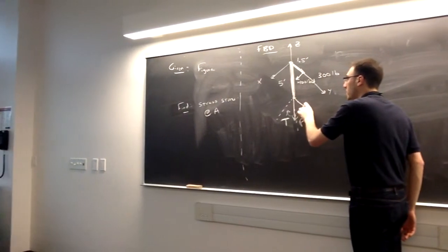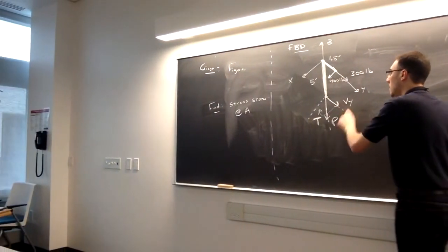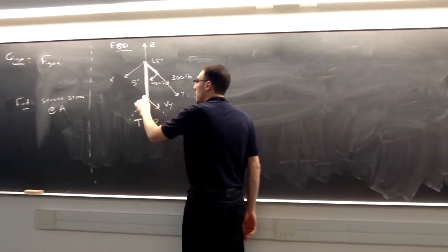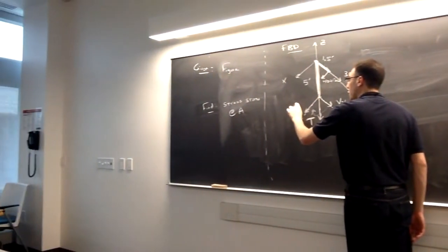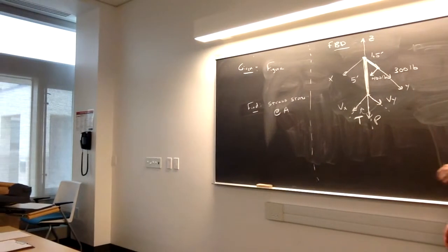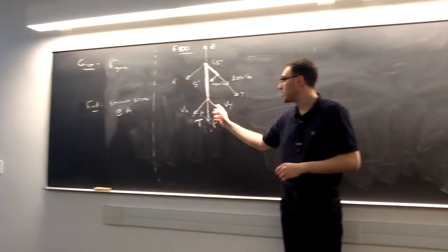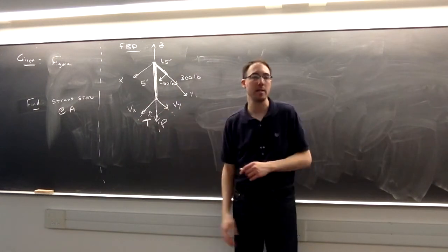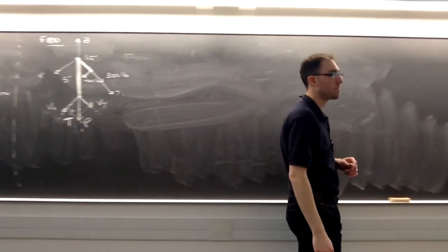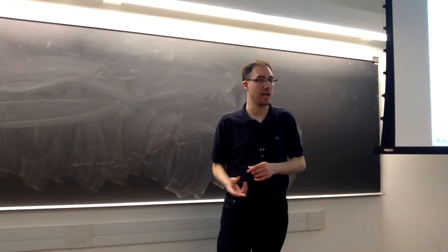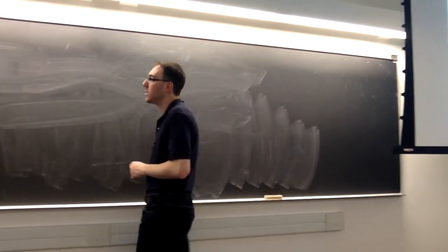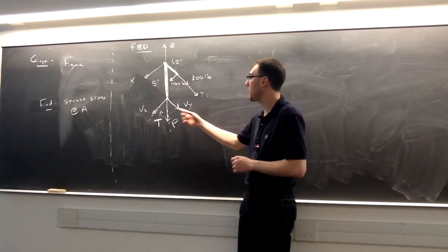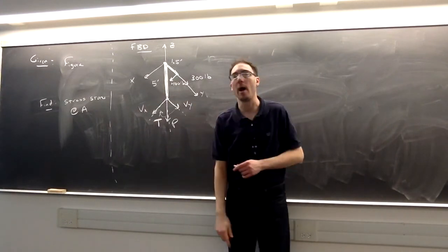One component of my shear force I can call Vy along the positive Y direction, and the other component I can call Vx along the positive X direction. The directions of these are arbitrary, but it's easier if I follow the coordinate system I've already established. But they have to be parallel to the surface of the cut. The surface of the cut is in the XY plane, so that's why I can split it into an X component and a Y component.